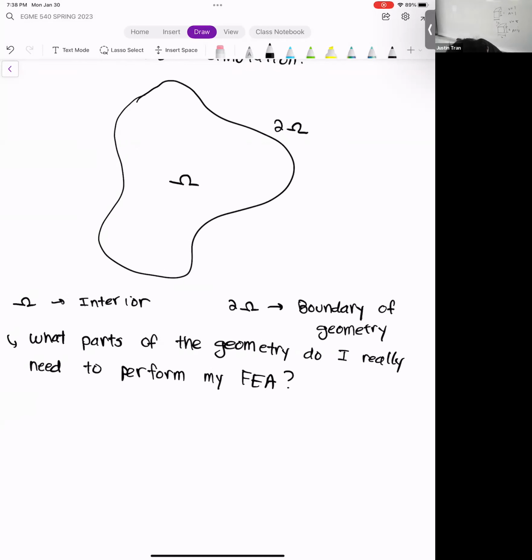Shouldn't be applied to assembly as a whole, but sometimes you have to do a whole assembly. There are situations where the entire assembly has interesting stresses or deformations, or maybe the connections between the parts are hard to model with just the individual parts. So every situation is a little bit different. You can do assemblies, yes. And in fact, our next activity is going to use an assembly.